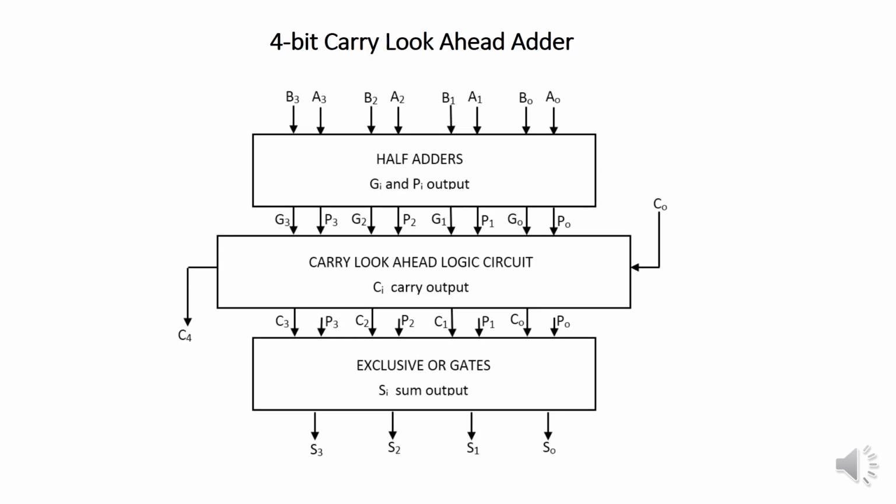This is again the same circuit in a more block format. The block of the half adders to produce the G and P functions, the block of the carry look ahead to produce the carry outputs, and the block of the exclusive OR gates to produce the sum outputs.